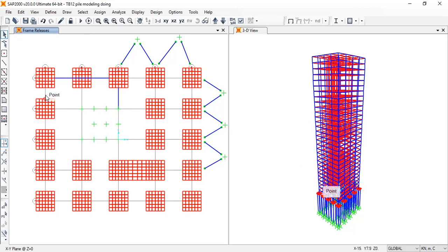Already these pile caps should be connected in X and Y direction, similar to this, from pile cap to pile cap, if there's a combined pile cap. And here to here also, here to here. Then the structure is fully completed. Okay, we'll see the next time. So modeling is completely done, including the pile foundation, and the wind load, everything's there. You will see when the wind comes, sometimes there will be piles in tension, sometimes piles in compression. So you can model this and analyze the results.